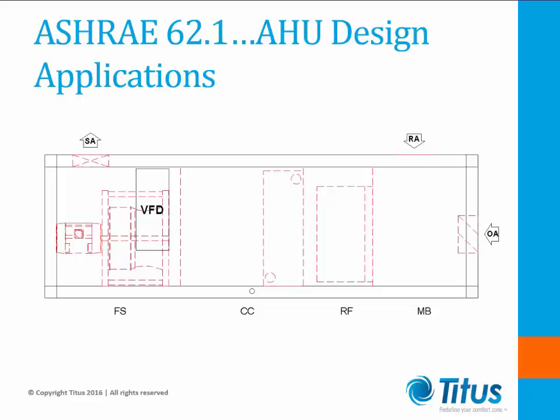Another topic is the call for access doors or panels for cleaning sections. Mixed air plenums and upstream surfaces of each heating, cooling, and heat recovery coil or coil assembly having a total of 4 rows or fewer should use some form of access, while upstream and downstream surfaces of each heating, cooling, and heat recovery coil having a total of more than 4 rows, along with air washers, evaporative coolers, heat wheels, and other heat exchangers, shall have access doors applied.